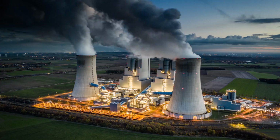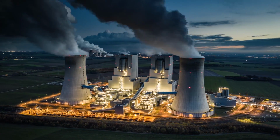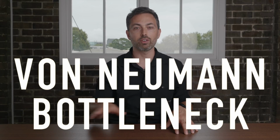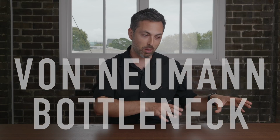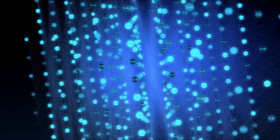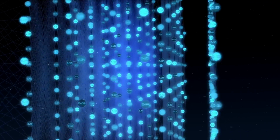And this is a problem for several reasons. One is energy consumption. Training a neural network requires an amount of electricity similar to the yearly consumption of 3 households. Another issue is the so-called von Neumann bottleneck. Virtually every modern digital computer stores data in memory and then accesses it as needed over a bus. When performing the huge matrix multiplications required by deep neural networks, most of the time and energy goes into fetching those weight values rather than actually doing the computation.